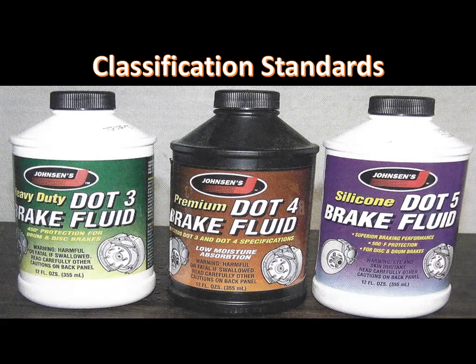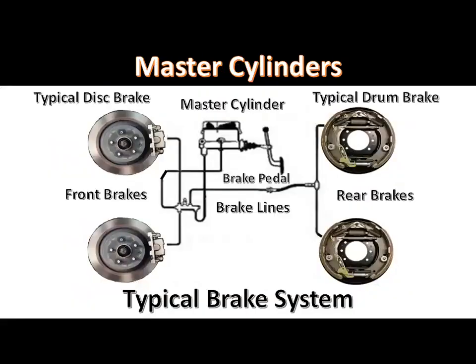Brake fluids in use today are DOT 3, DOT 4, DOT 5, and DOT 5.1. The purpose of the master cylinder is to supply brake fluid pressure to the wheel cylinders or calipers during a brake application. If fluid pressure is not available in one section of the master cylinder, fluid pressure in the other section is applied at two wheels to stop the vehicle.